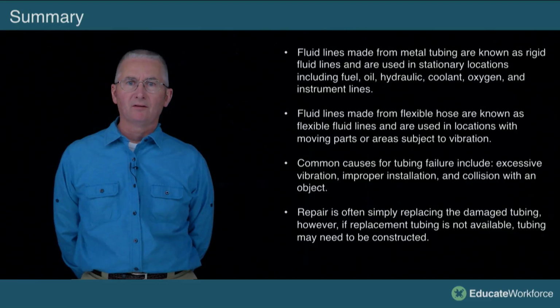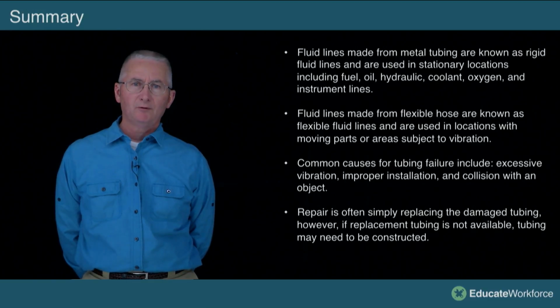And then the repair of the line. Again, we'll follow what the advisory circular, the AC-43, tells us we do. Sometimes if we have a scratch or a dent, we can do some tubing repair. Sometimes it's just easier to replace the line.